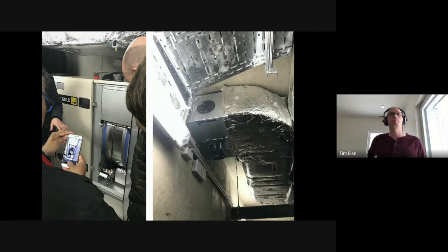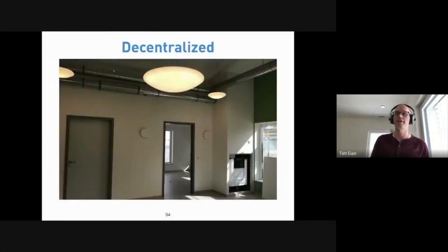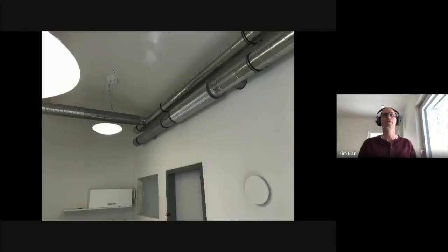When you get to multifamily, you have choices. You can do it centralized. You can do it decentralized. This was a system in a daycare facility right here, and you can see there's just this closet-looking area with a Zender unit in it on the right-hand side. In this particular building, there was an addition put on, and so centralizing the system wasn't practical. They also didn't have originally proper ventilation like many buildings here in the States. So what's happening here is they're basically placing individual units and then putting a small amount of ductwork for a certain area on it.